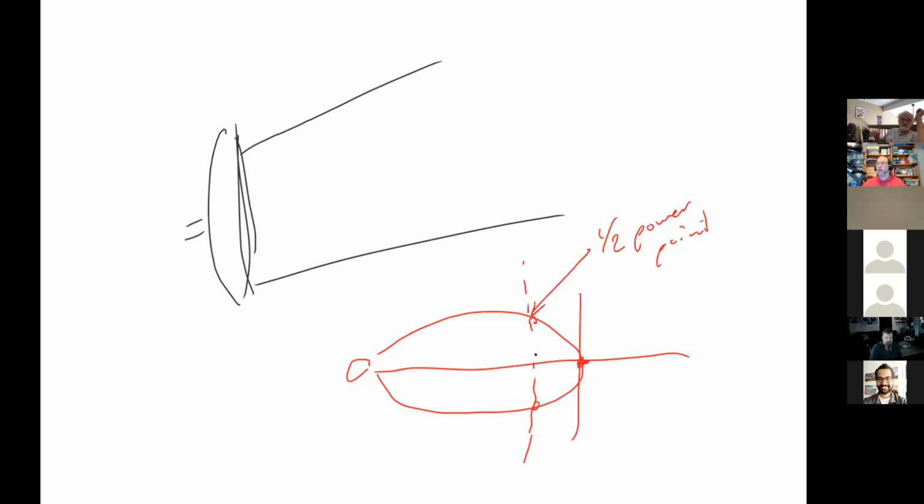How many dB would that be, everybody? How many dB down from the peak? 3 dB. That's actually known as the 3 dB beam width of an antenna. That's how we usually define the beam width of an antenna in degrees. Looking from here, that would be our beam width. There's the dish itself on the diagram, just overlay the dish. The dish would be right there pointing that way.